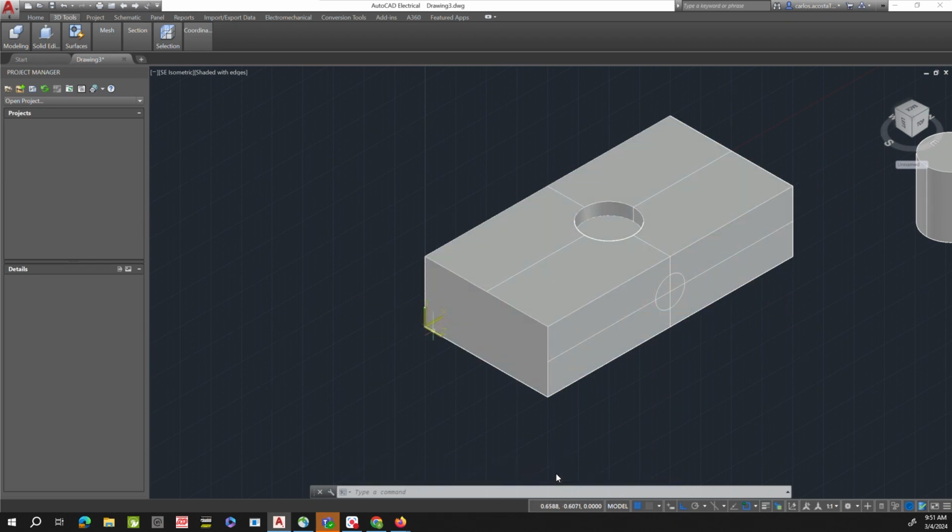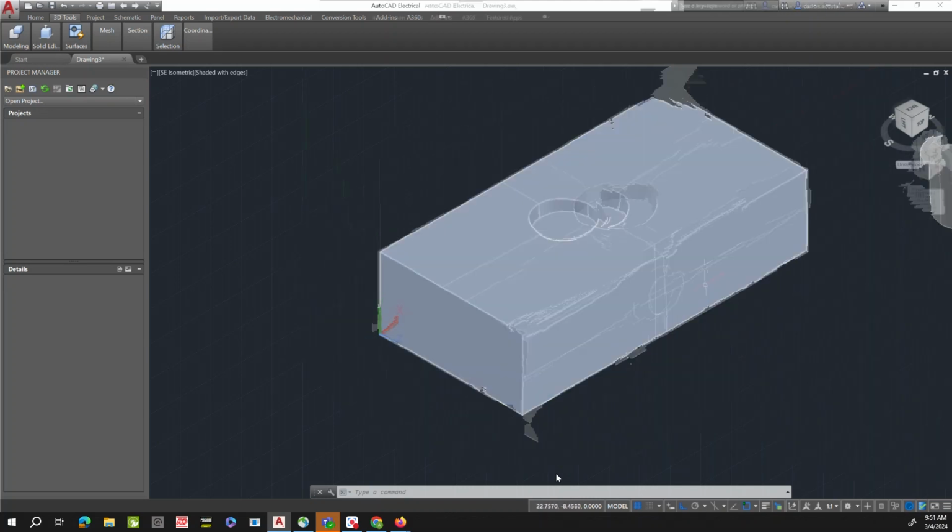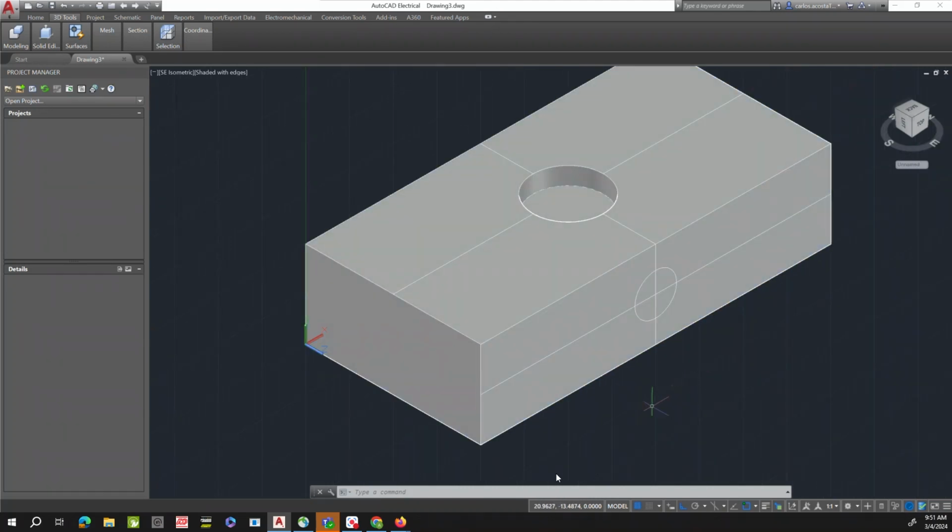So every time AutoCAD is going to use the z-axis as the extrusion axis and your x and y as your base axis. Same thing if you go to this side, then you change your plane to coincide with this face. Make sure that the z-axis is pointing perpendicular to the extrusion plane, and then with copy edges you select your intersection point.